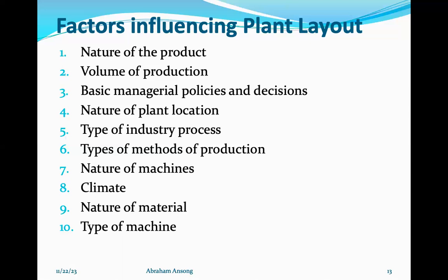So the type of machines that you're using also can influence the type of layout that you want to use. If they are heavy machines, normally you can't be moving them about. So you have to employ the stationary layout, where everything is brought together at one place in order to manufacture or produce that product. Okay.